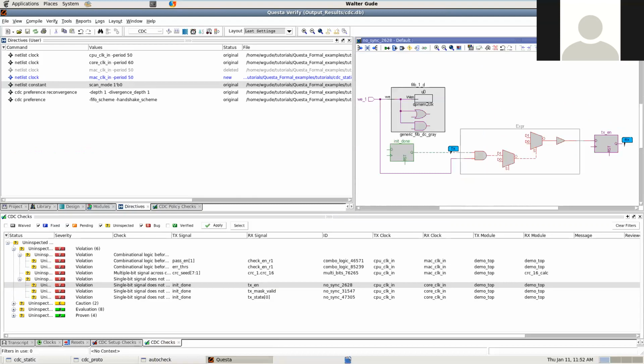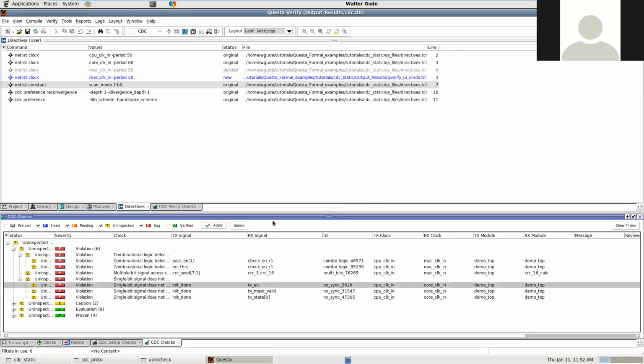And even worse, what I'm seeing is I've got a signal from this purple domain going into some logic from that green domain. This logic is highlighted as red because it's saying, hey, I'm mixing domains here. That's coming in, and I am going to have problems here. So that's definitely a problem. I've got to go fix that.